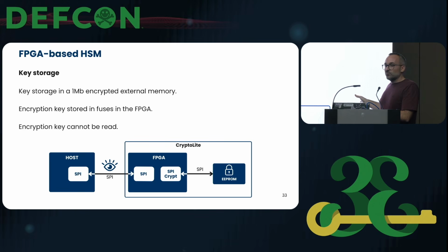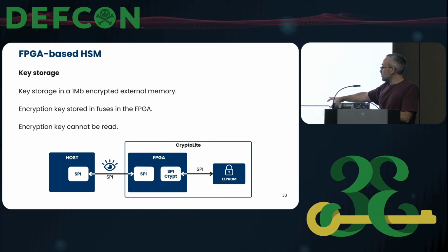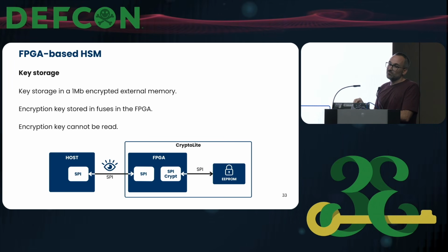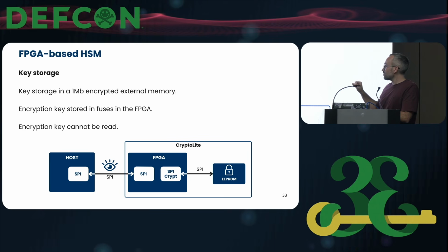And regarding the key storage, well, it is easy. I just need to add an EEPROM memory to the board, for example, and then I can use an SPI driver that encrypts all data that I write in the EEPROM memory. The key, in this case, can also be stored in fuses inside the FPGA, so it can also be write-only. The encryption key cannot be read.